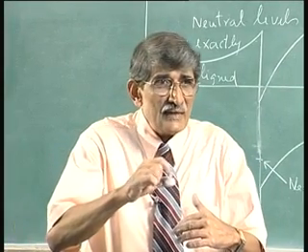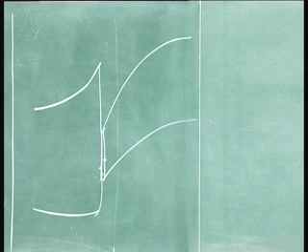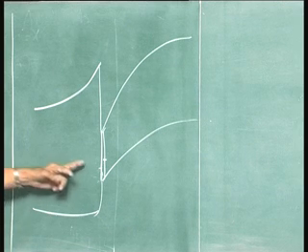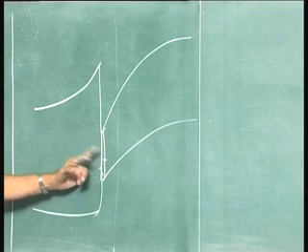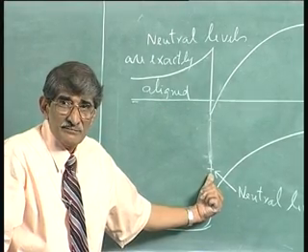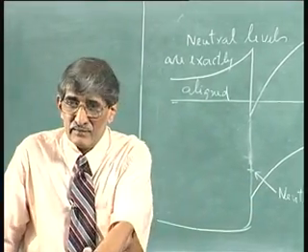This is what you have said here, just as a statement, but ultimately what happens is each one of them forces the level to align to each other. If the line up does not occur, charge transfer takes place between the states on either side of the interface, and this will create a dipole field. From the energy considerations, the system favors dipole minimization and therefore equalization of E naught levels. That is as a statement I have put there.